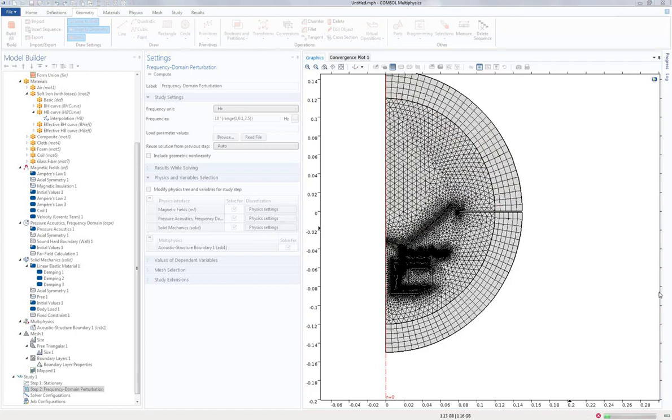What do we have? Hello, I have a situation that requires a helium atmosphere. How would I implement that instead of air on the front side of the baffle and contain in a tube resonator closed system? Well, you would just select helium instead of air. That's one of the materials that we have prepared for you. That's easy. But then you would also need to make sure to model this tube resonator closed system by effectively just drawing it, I guess. That's the easiest way. You can probably simplify it if it's very complicated, but what you don't want to do is use PMLs like I did, because that would be an open system.